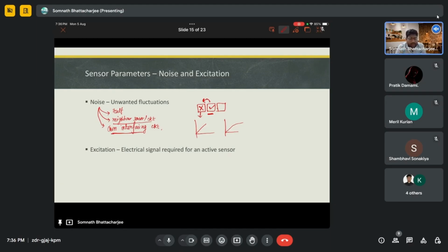So you need an amplifier to amplify those values and use them in the usual cases. The transistor can have noise itself. Because of that, the value of the piezoelectric sensor will change, and it will induce noise in the signal as well.